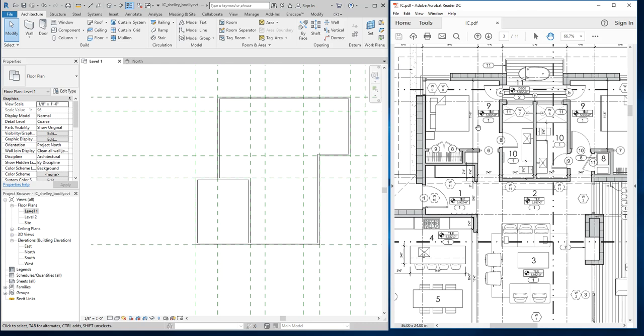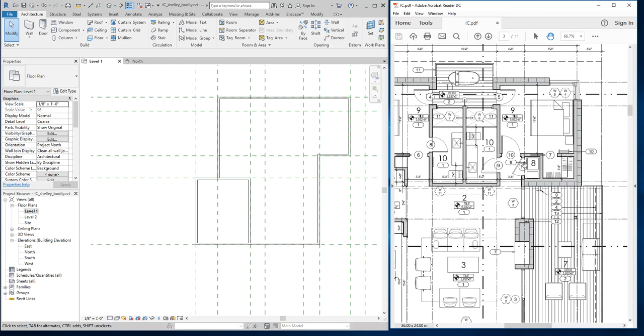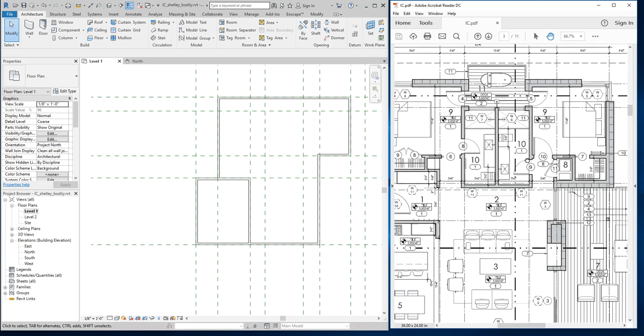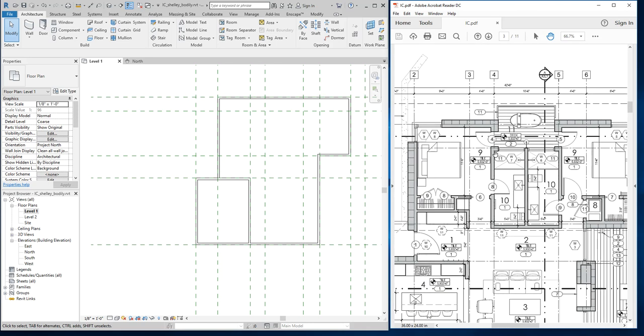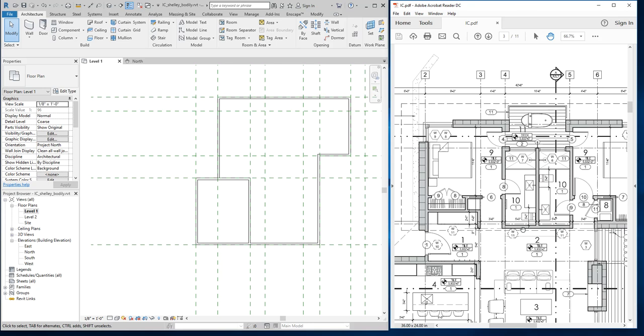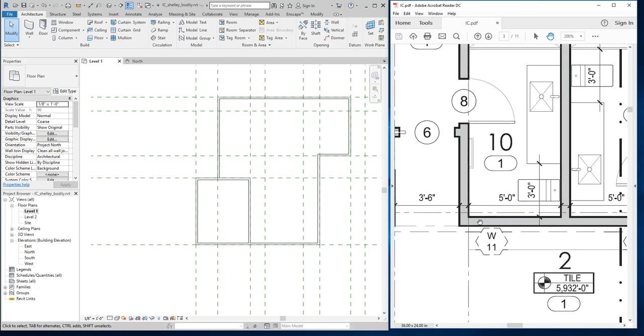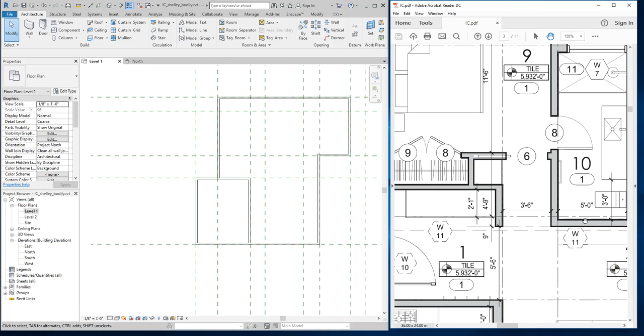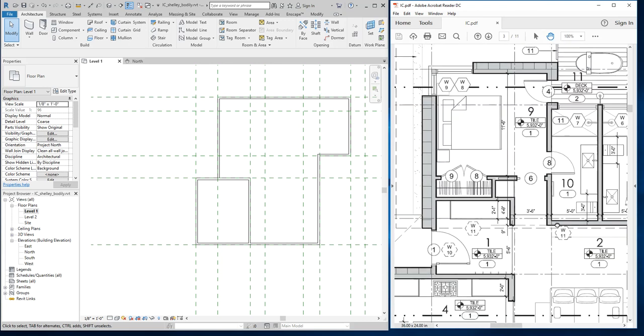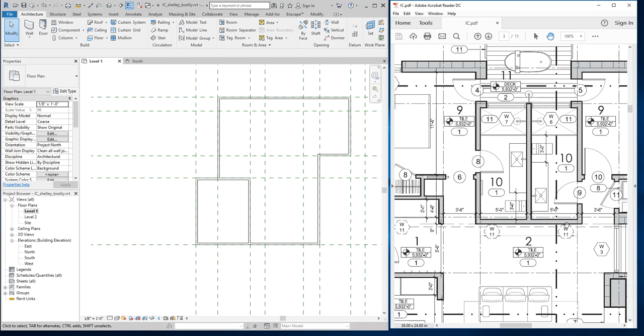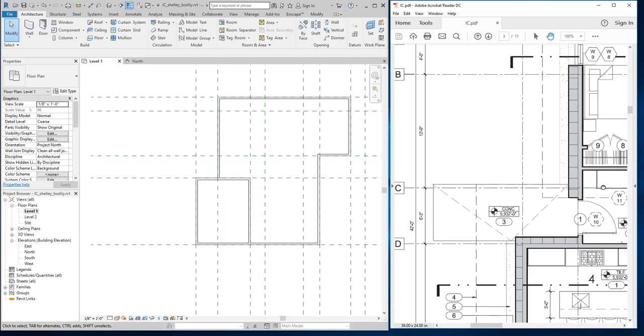So I'm going to come up here and start drawing interior walls. And of course I always like to go to the easiest spot, right? I'm looking here and I'm thinking these bathroom walls lie right on the grid lines, so I think I'm going to start drawing those. They go between grid lines 4 and 5, and they go all the way down. Ooh, just a tiny bit past. So why is that? We're going to figure that out. But I'm going to get it as close as possible. I'm likely going to draw that on the grid line and then figure out where it actually needs to go. That goes down to grid line C.